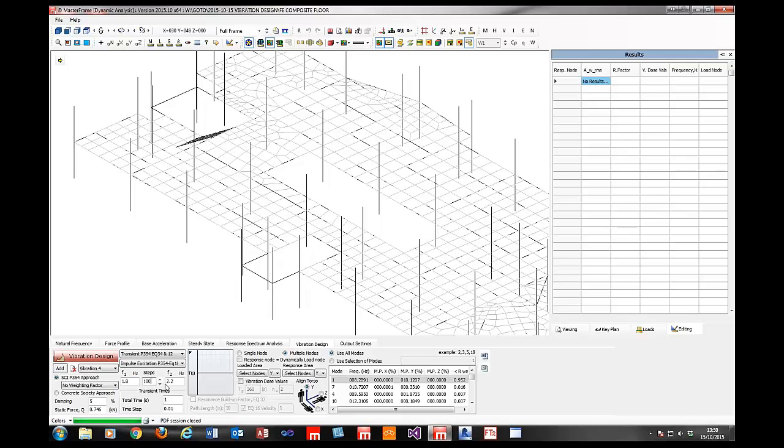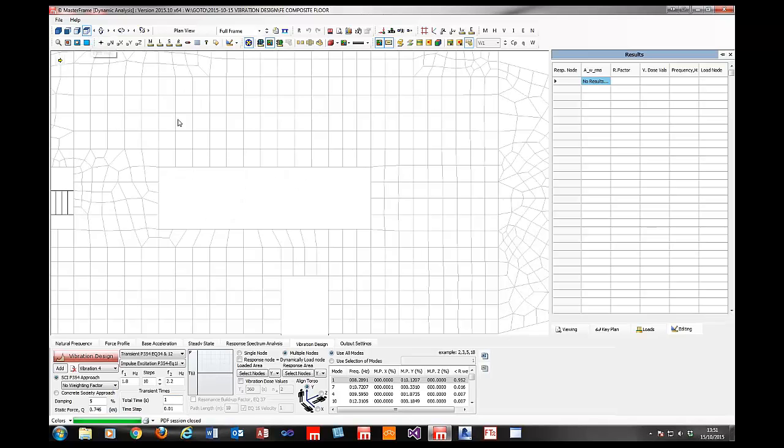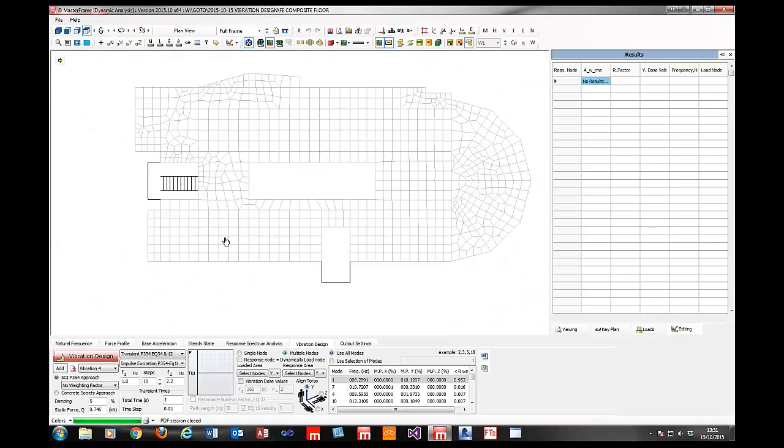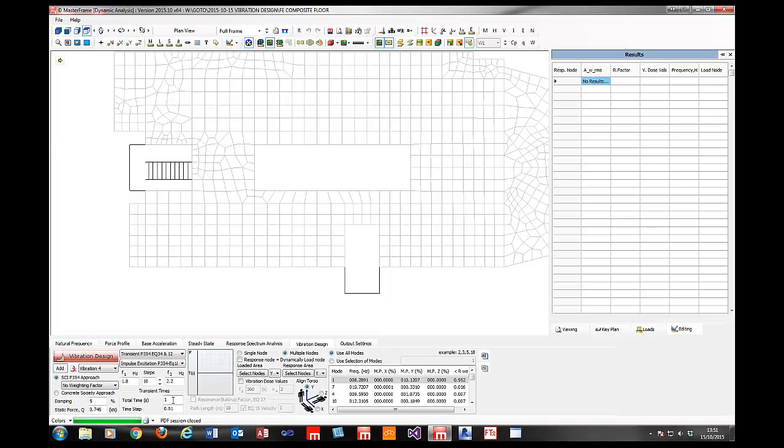And in this case, you really do need to be conservative about the steps that you use and things like that, because the transient analysis is a full time history analysis operating at lots of different time steps over a set period, and as such it will be much more computationally extensive and expensive than the steady state analyses. So the total time over which we're going to measure this acceleration is again dictated in P354 as 1 over the fundamental walking frequency.